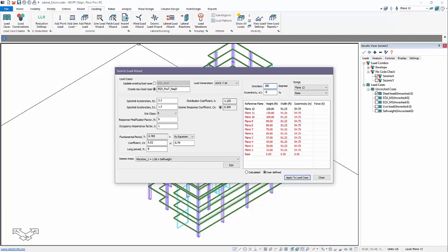You could also plus minus inside of the load combinations. That's another way to handle this. So we'll change this back to 5 and I'll apply that. We'll then go back and change this to negative. So decide what your own notation is here. This is just shorthand notation for what we're trying to describe in terms of the loading. And we'll call this -5.